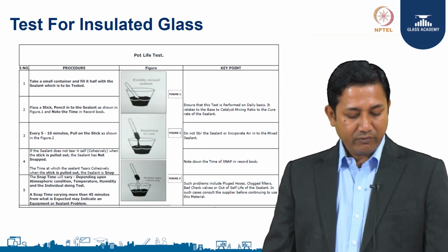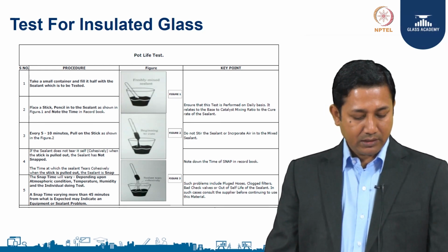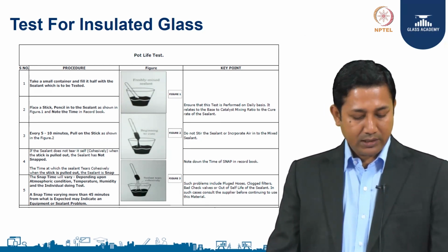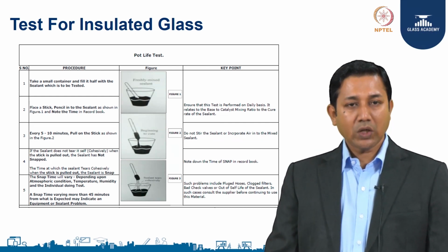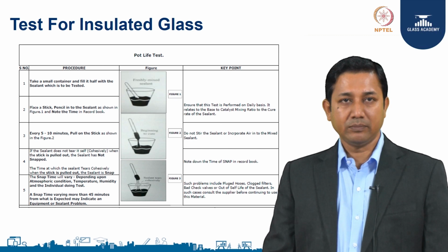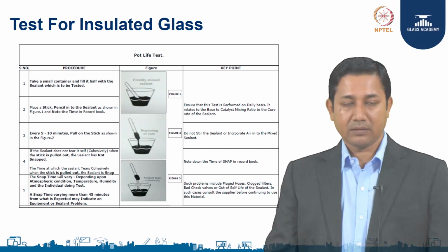A snap time varying more than 45 minutes from what is expected may indicate that the equipment or the sealant is having a problem. So, you have to retest it.